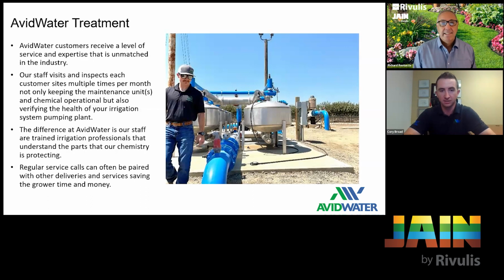If I notice something on a service report where I go, Richard, the pressure's up a little bit and your flow's down by 50 gallons a minute, maybe you haven't seen it yet in the field, or the guys just haven't found where it's happening, but we need to look at something, that may hopefully set into motion a flushing protocol. Where you can say, okay, I'm going to have my guys go out and perform some infield service. Or, hey, Cory, can you do it? Because I don't have time, or I don't have the manpower. It's just those opportunities to be able to look ahead of it.